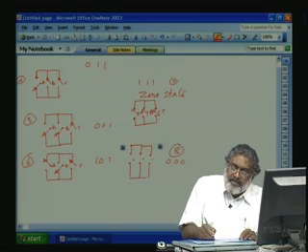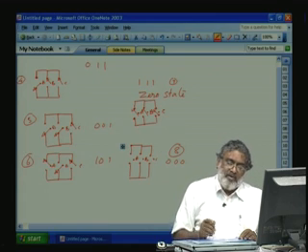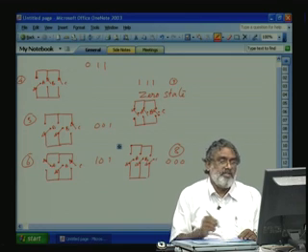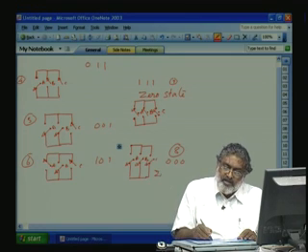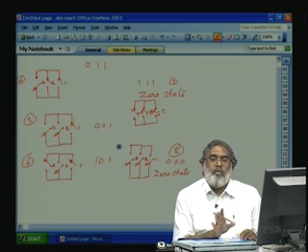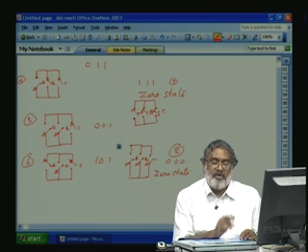Here all the 3 poles A, B, C are connected to the bottom rail, that is the bottom switch is on. This is also called a zero state. So for PWM operation, during one operation we can only have 1 out of these 8.